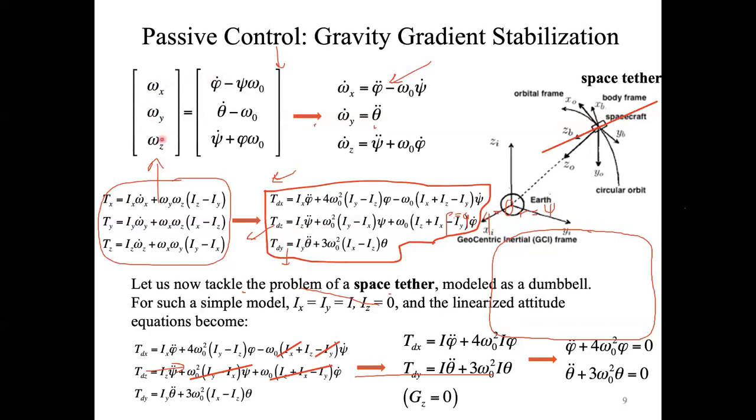So what we have written here, this expression of the angular velocity with respect to the roll, pitch, and yaw angles, can also be computed for the time derivative of the spin angular rate. So what we are doing here is the derivative over time of omega x, omega y, and omega z. So you can find that this expression is indeed phi double dot minus omega 0.